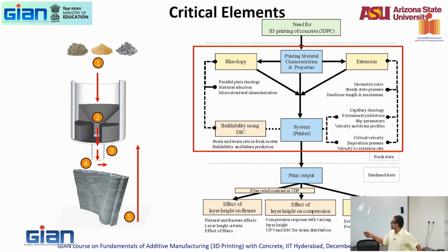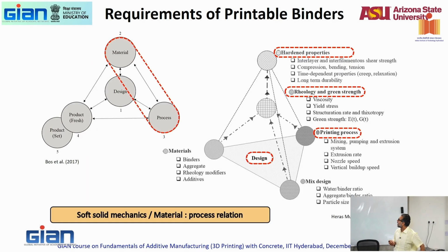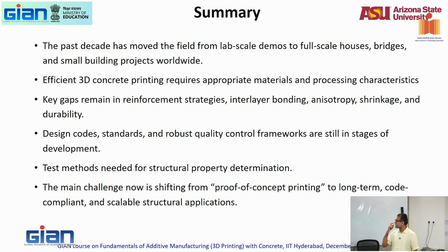So a lot of different early properties: the rheology, which we will see, extrusion itself, the system which is part of it, how do you know how buildable it is, and all of this you will get an output, which is hopefully what you want. And then in that, you want to know what the flexural properties are, what the compressive properties are, what the quality is at a later date. Hardened properties, rheology principles, same idea. So some of these things we will see in the afternoon.